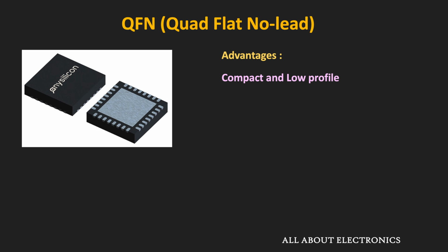Moreover, on the bottom side of this package, in the center there is a metal pad. And this pad directly comes in contact with the PCB. And due to that, it helps in dissipating the heat efficiently. So that is the reason this package provides excellent heat dissipation.